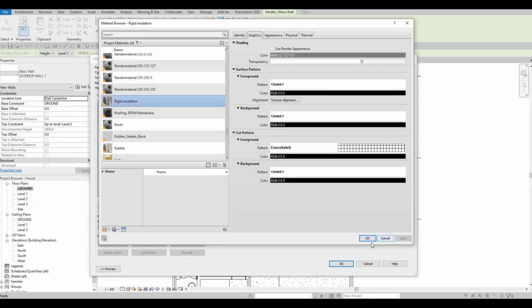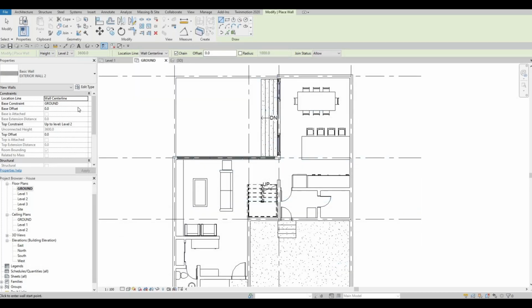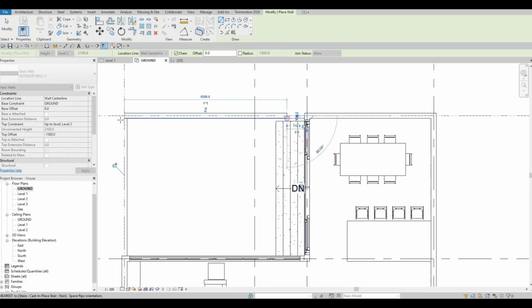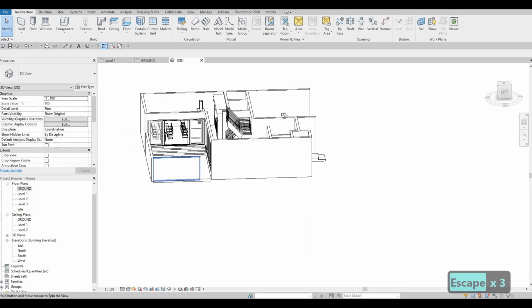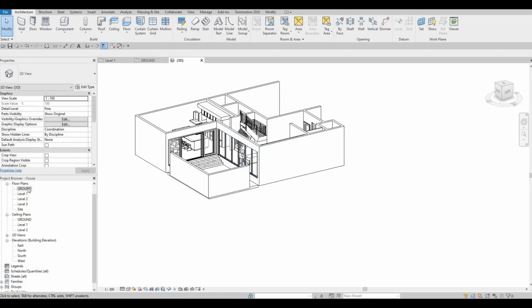I'm just gonna use this. And then after that, ground to level 1. I know level 2, but there will be a top offset so that it's not too much. So it should be negative 1500. So here I'm just gonna add it. I'm not going to stick it yet to the wall because I know I need to verify this first. So I like the height.